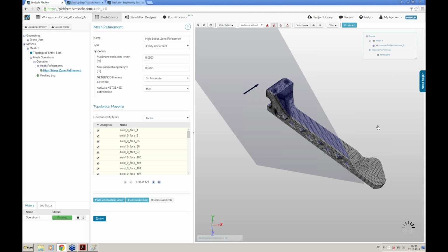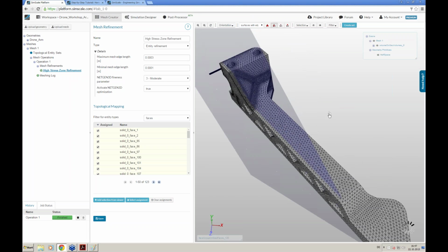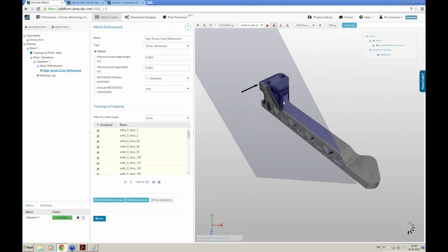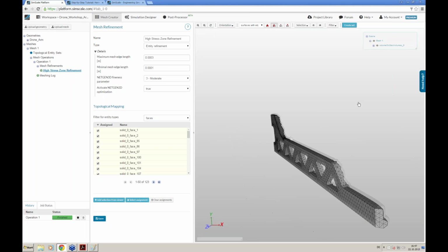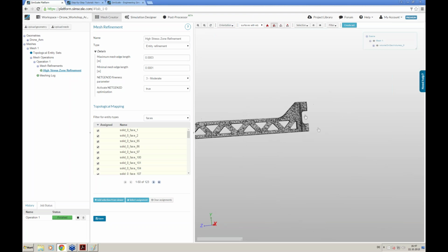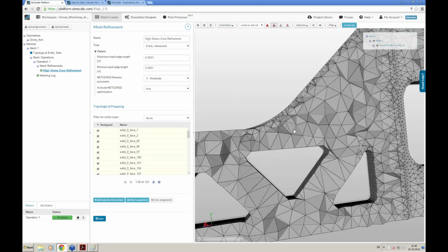And this sometimes takes maybe a minute because now the mesh has to be processed. Everything which is computing intensive is not done on your local computer but in the cloud, so you are independent from the performance of your local computer. And then we can even take a look inside of the mesh, like here. Double click with the left mouse can help you change the center of rotation, and now we can take a look into the inside of the mesh.